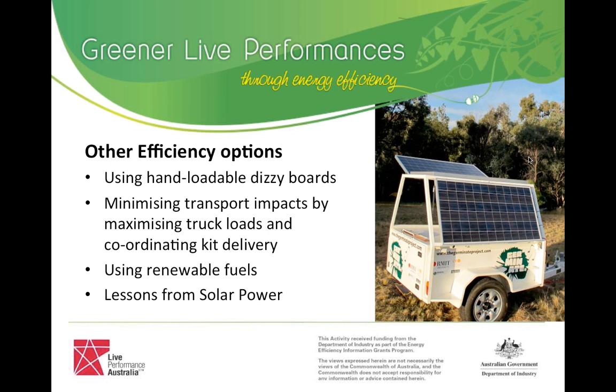Yeah, I think from our perspective, one of the biggest pieces of advice that I can give to everybody, and it was just highlighted in the solar information, is that the actual connected load that we see on the generators is generally grossly oversized. So when you create a set of load profiles for your event, the information you can get from stall holders or audio people or lighting people is very, very important in assisting in determining what is the best, most suitable generator.